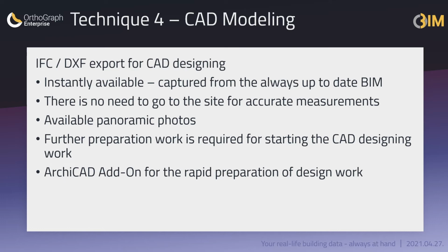It only contains that information that is needed for decision making, for tendering or for workflow support, for example for maintenance management. This means the IFC generated from an Operational BIM will not contain slabs or typically pipes and tubes, as measuring these items costs money and are rarely required for the everyday operational work. So with minimal manual work, by importing the IFC files generated as a snapshot from the database of Operational BIM is a very good basis for preparing a BIM that is further usable for designing and planning.